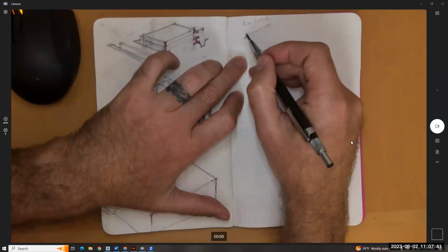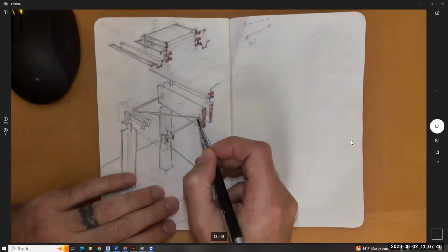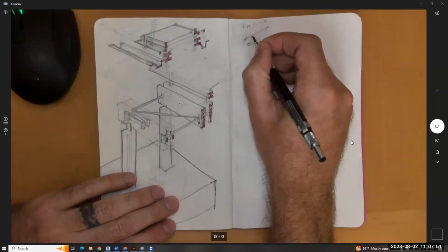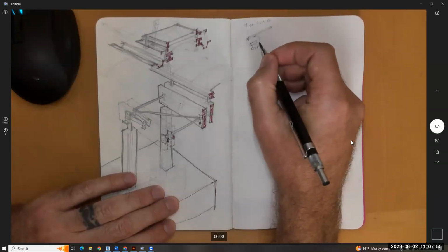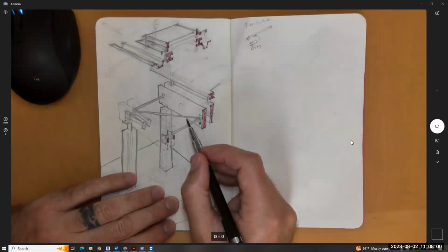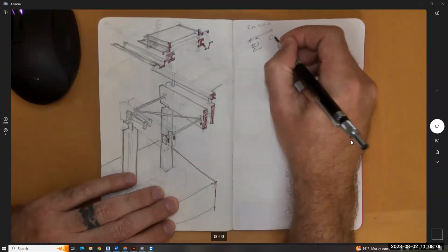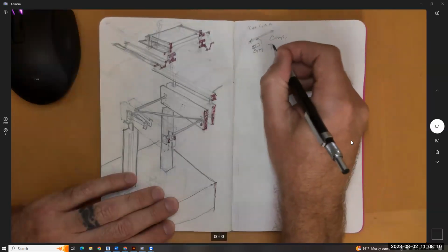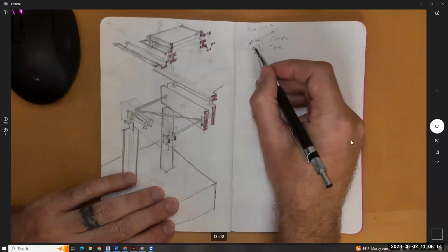Now we're going to have some fun and build little end caps for them, like little connectors, that we're going to host onto those. And these are going to be generic models, just straight generic models. They're going to be caps hosted onto our pipes. But we're actually going to want two different sizes. We're going to want a compression version, which is bigger. Those are the ones crossing this way, and a tension version, which are going to be really small going away. So we're actually going to want two different knuckles, a big knuckle and a small knuckle.